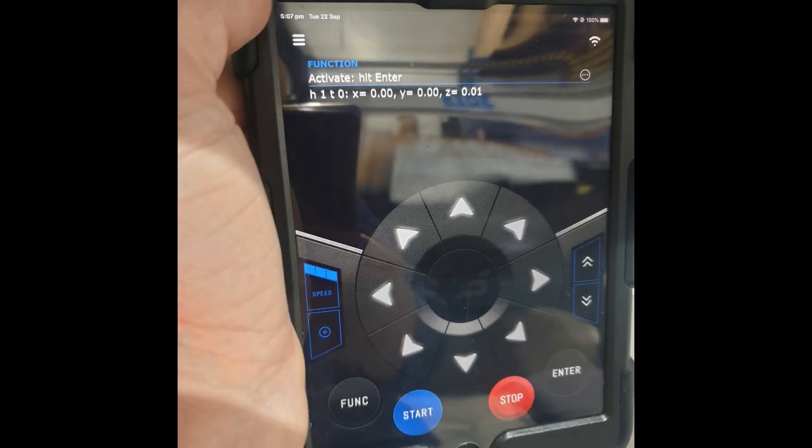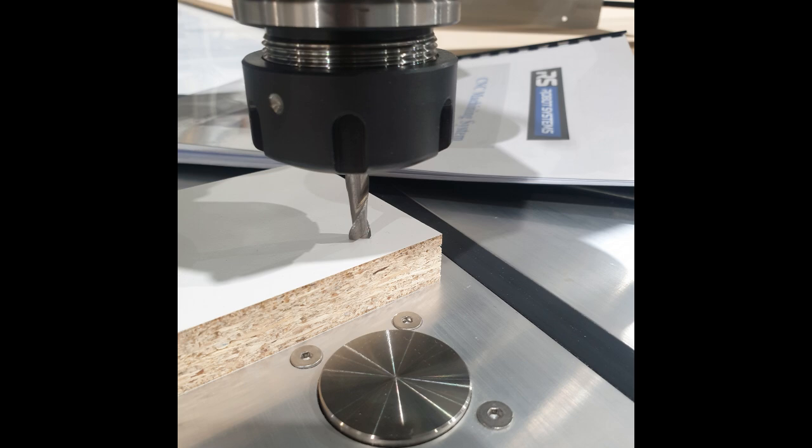Lastly, we'll set the calibration surface. The calibration surface can be any surface on the machine that does not change in Z height. The calibration surface is not generally used after the tools are initially set up. In this example, a piece of melamine has been used on the tabletop surface, as this is a repeatable height.